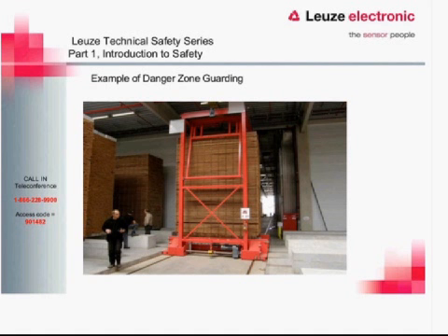So in this type of a situation, we have a rotoscan. You can't really see it great in that picture, but you have a rotoscan there, scanning for a distance in front of this. I'm assuming there's also one on the back side of this machine. So as the machine moves, the dangerous area to stay out of moves along with it, and if somebody were to walk in front or behind this machine, we'd get a signal to stop the machine safely.